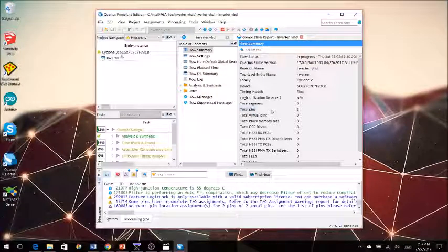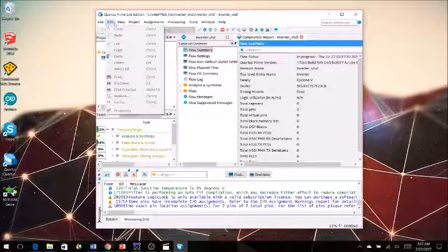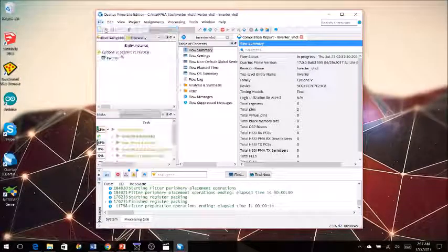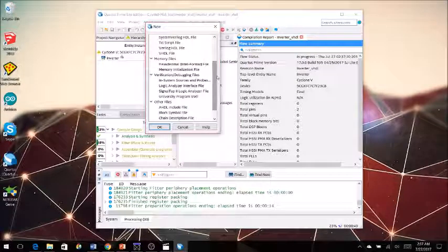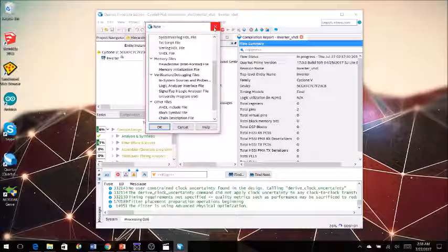So the next thing we'll do is, once this is done compiling, we'll come up here and once again open a new file, and we'll go to University Program here, and we'll open that, and we can simulate our virtual circuit, I suppose you could say, and just see if it's working the way we expect. It's a good way to test it.